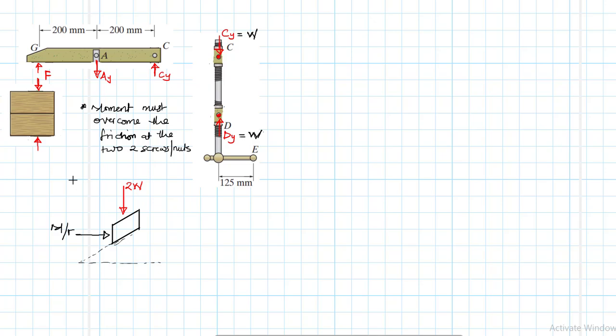So it's moment divided by the radius of the screw. And then, what else? As we do so, we are going to expect friction, and friction of course will be in the opposite direction of motion. We expect F like this, and we expect our normal force like this. But instead of using this, we are going to use the resultant force R.